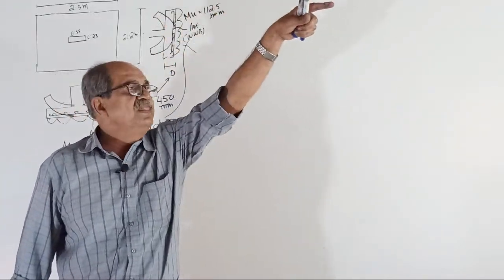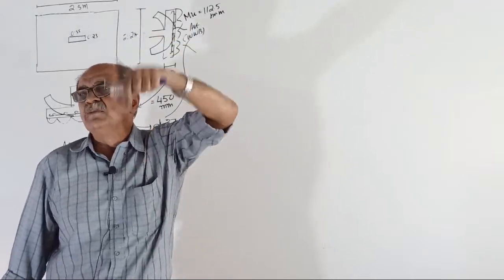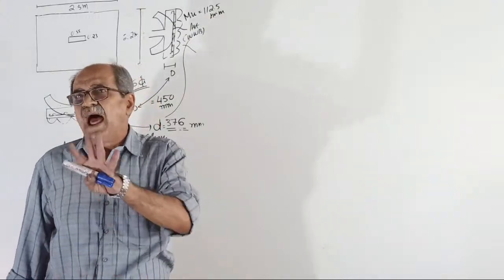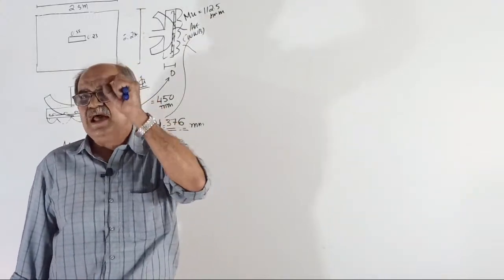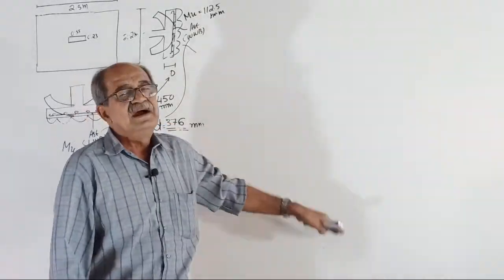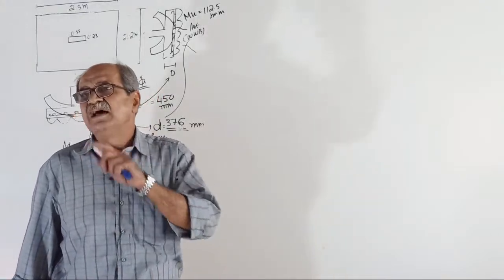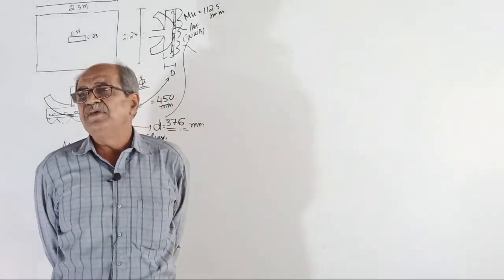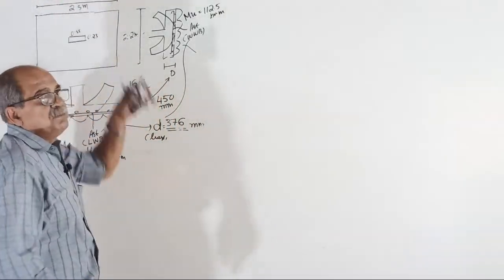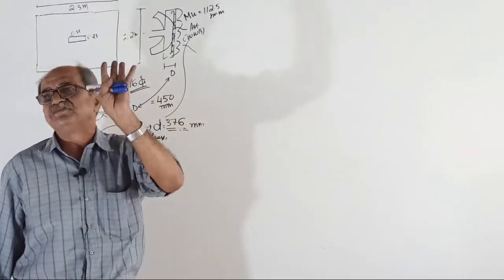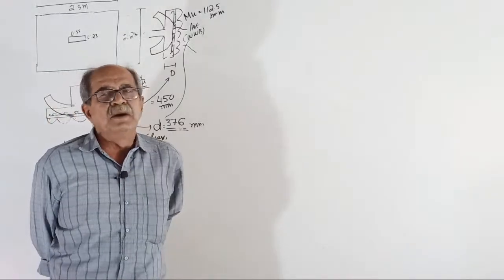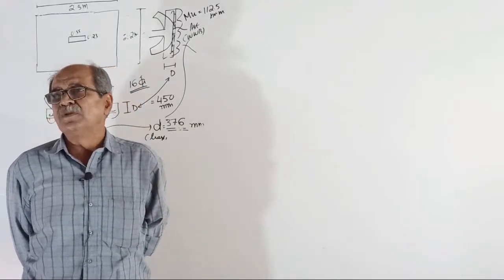Later, when I design the footing for a column with axial load and biaxial bending, that is the practical problem. Initially, I will deliberately take a little lesser depth, so that redesign comes there and you will learn redesign. And when you design by SAFE, you need not bother about punching shear, because the punching shear check is performed by ETABS and SAFE. It will give a number. I told you what that number is, and that it should not be more than how much?